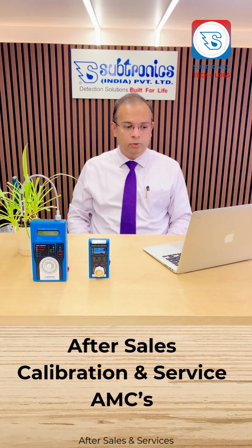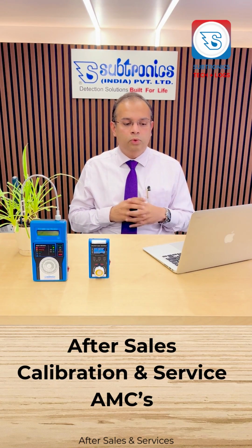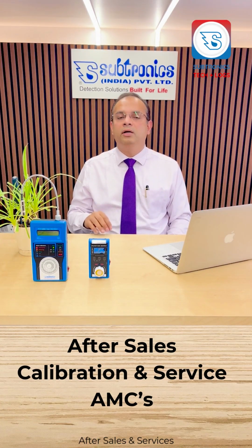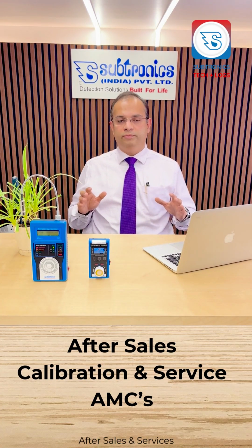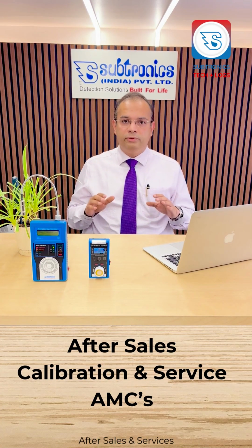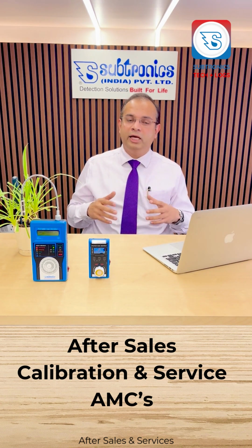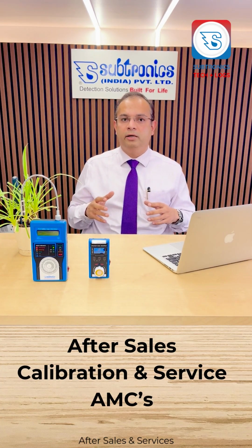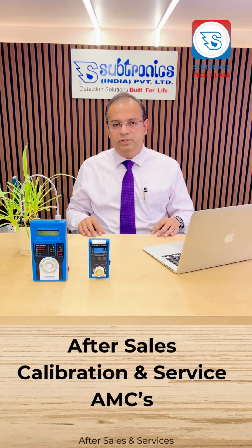The most important part now, what I would like to elaborate, is the after sales. That is the most important thing. To sell a product is okay, but what about the after sales service? We are known in the market today for our after sales service, the prompt service that is required once there is any difficulty faced by the client. All the systems that you see, any kind of gas detector system, will require calibration. Calibration frequency of most of our devices is minimum 1 year. We also do maintenance or calibration services monthly at some particular clients where the gas is very critical and requires to be calibrated monthly. So it may be monthly, 6 monthly, or a yearly visit. Yeah, so we do those.